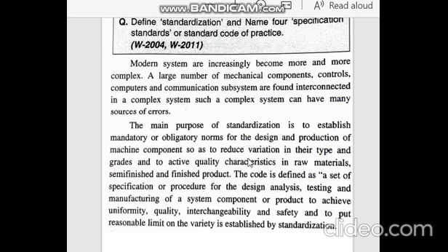Spanners have different numbers on them, so they can open the nuts of matching size. You can find a 10 number. That means 10 mm is the distance between the two straight, parallel faces of the spanner. And you cannot find a 10.2, 10.3, 10.5, like that.